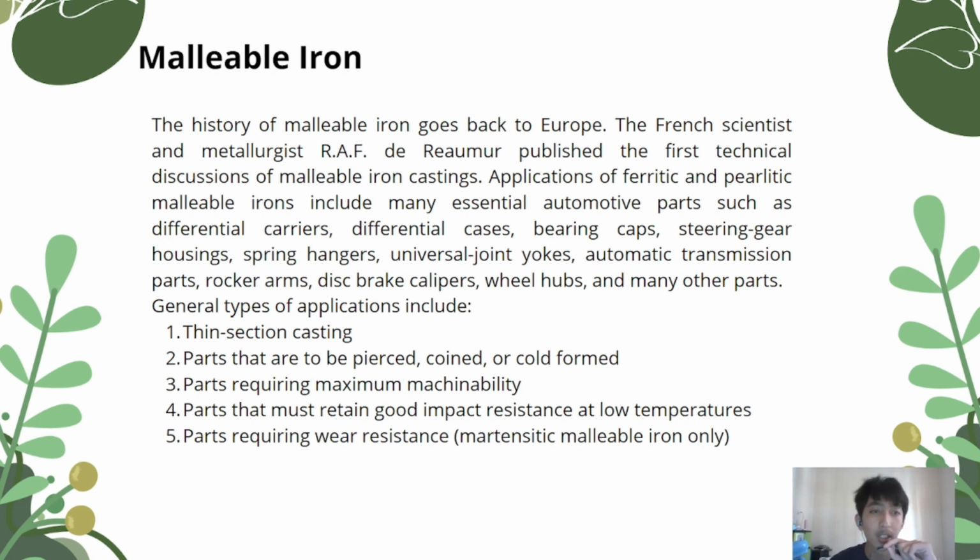General types of application include: the first is thin section castings to be pressure tight or hole formed. And next is parts requiring maximum machinability, next is parts requiring good impact resistance at low temperatures, and finally is parts requiring wear resistance, or magnetic or non-magnetic malleable iron only.